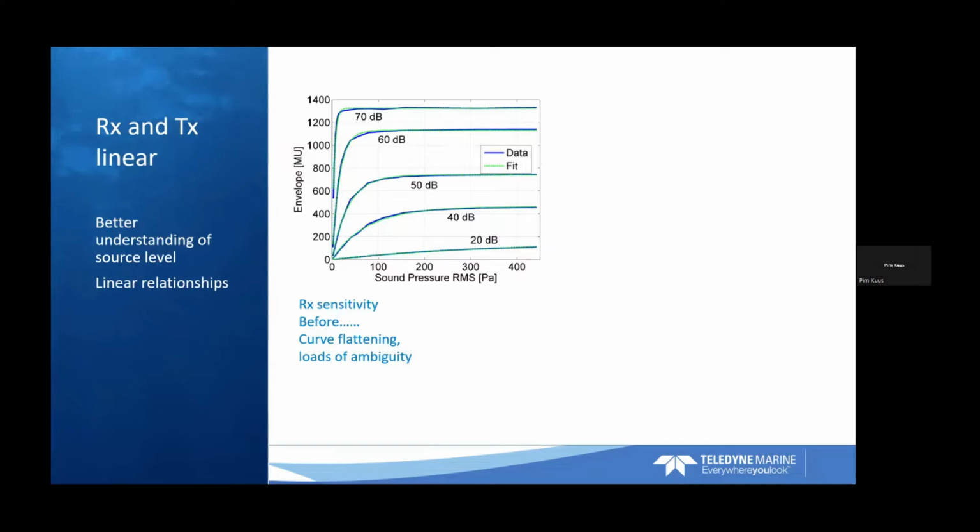But it's important to realize that a multibeam doesn't really measure dB values. At transmit we send an electronic pulse to the ceramics that converts it to an acoustic pulse that interacts with the seabed. It comes back, and at receive the opposite happens. The acoustic pulse excites the ceramics, and that converts it to a tiny voltage. And then that goes through a lot of processing to ultimately give you a backscatter value in dB.